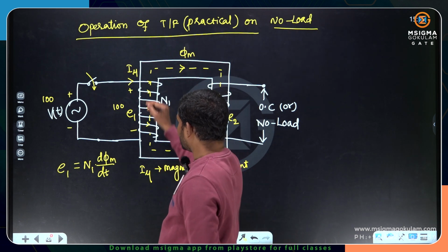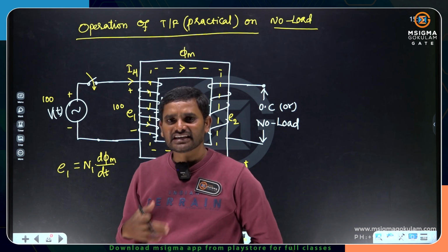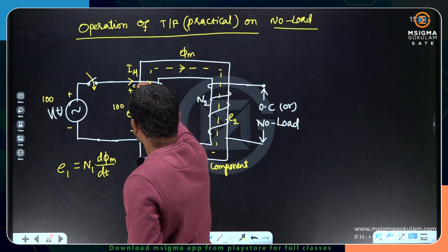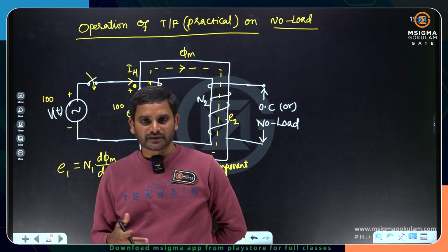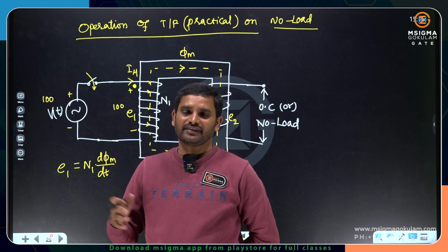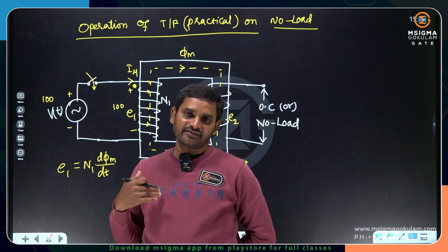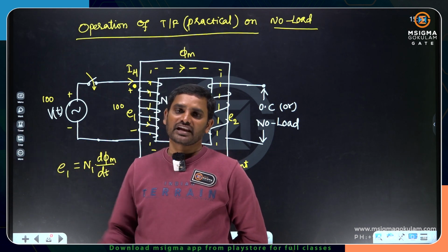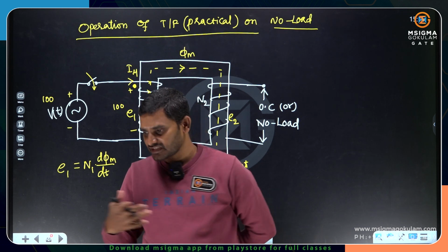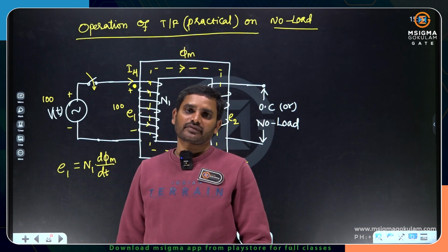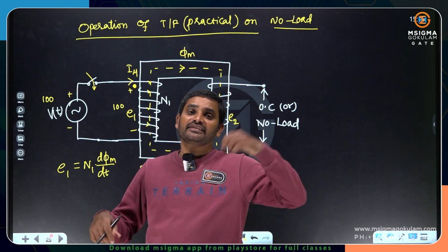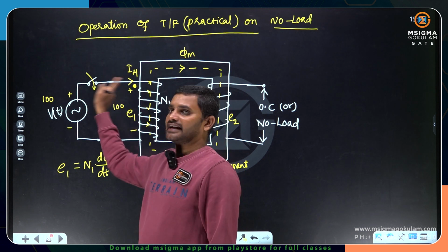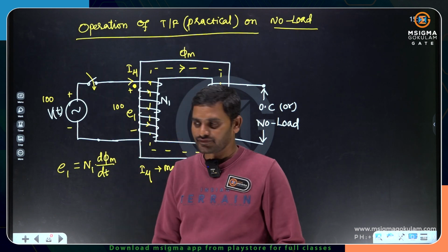So no doubt here it is the positive terminal and the negative terminal. Generally the positive terminal is indicated with a dotted terminal. We will take the dot terminal as the positive terminal for the connection purpose, for our convenience, because once the transformer is designed and sent to the market or to the utilization point, we don't know which terminal is positive and which is negative. So they will put some dots. By observing the dots, we should assume that they are positive terminals. That means the phase should be connected here, not the neutral. You have to understand it like that.